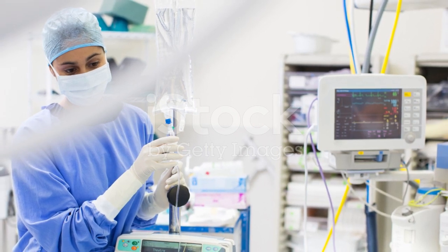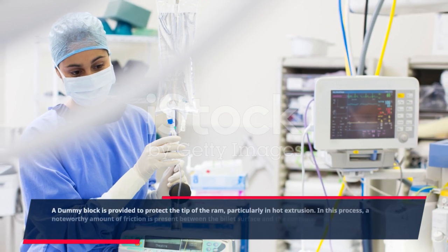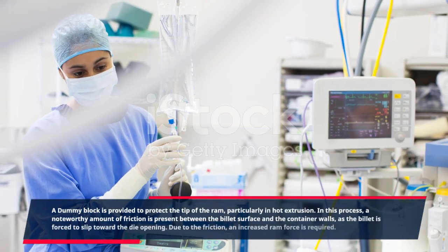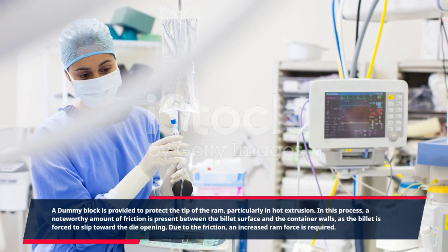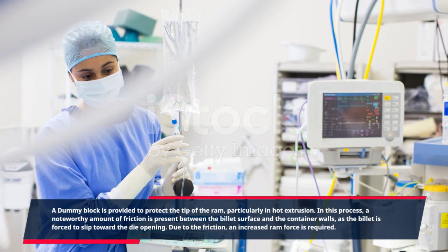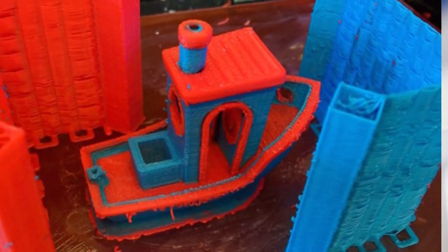A dummy block is provided to protect the tip of the ram, particularly in hot extrusion. In this process, a noteworthy amount of friction is present between the billet surface and the container walls, as the billet is forced to slip toward the die opening. Due to the friction, an increased ram force is required.